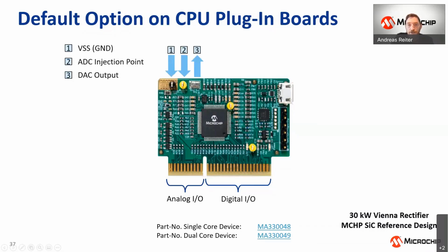And then in addition, you have here on the upper left corner the interface where you would wire up the Bode 100. So pin number 2 here in the middle, the yellow one, is where you inject that error signal directly into the ADC. Pin 1 is ground, and then pin 3 is the DAC output where you read the response.